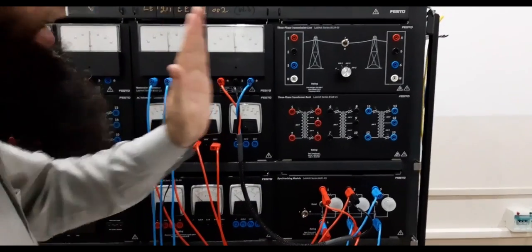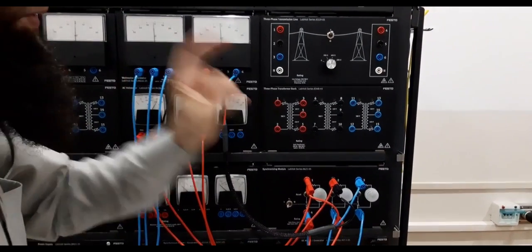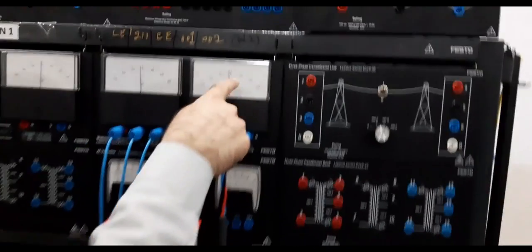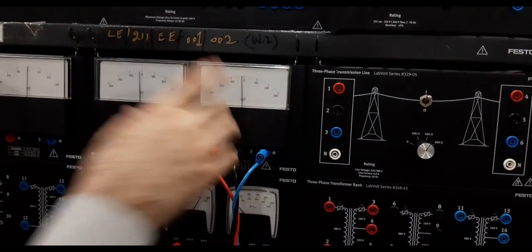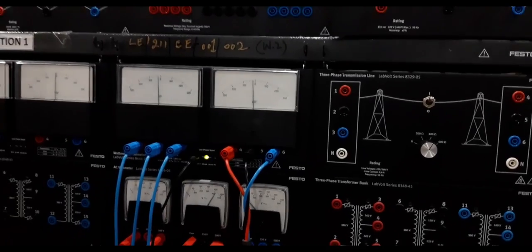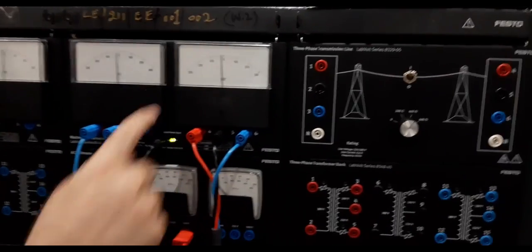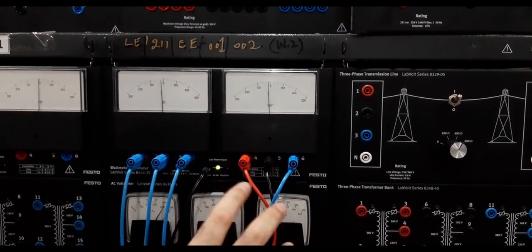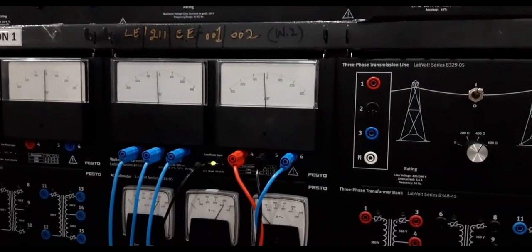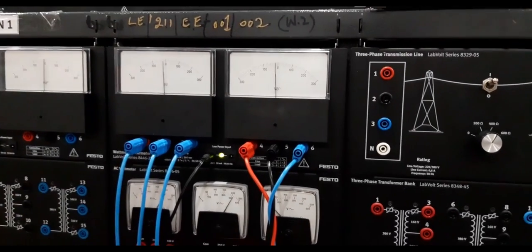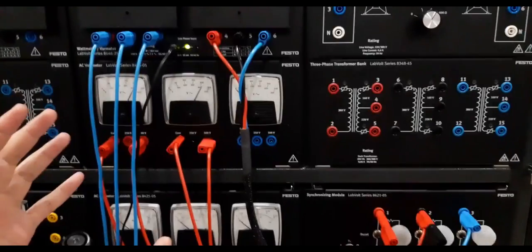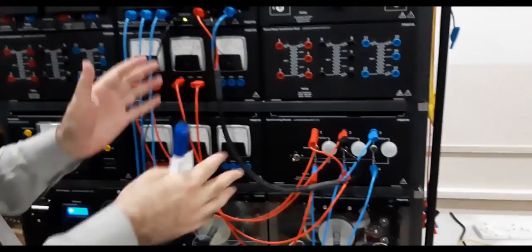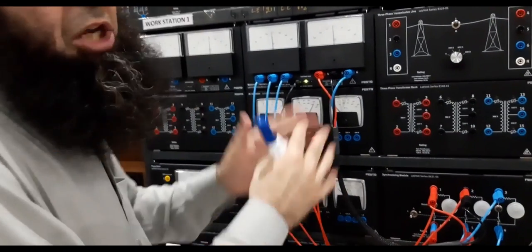And again, an important concept: by changing the direction or the sign of the reactive power, the generator remains the generator, the motor remains the motor. It either provides the reactive power or consumes the reactive power, depending on whether we run it in the underexcited case or in the overexcited case. But the nature of the machine will not change. So with this session now, I end the discussion on the synchronous machines and rotating magnetic field. I hope you understand. I hope it will clear your concepts even more.